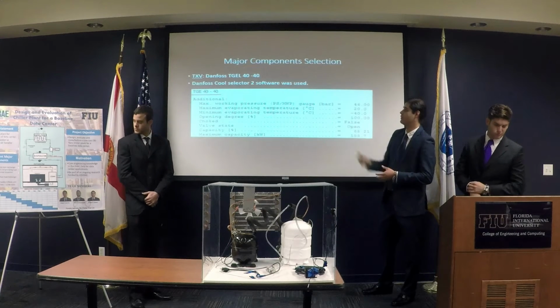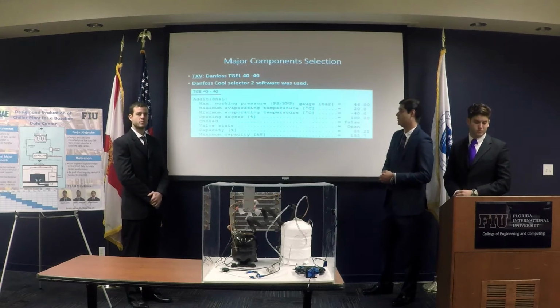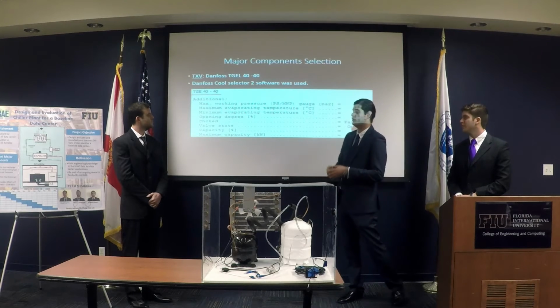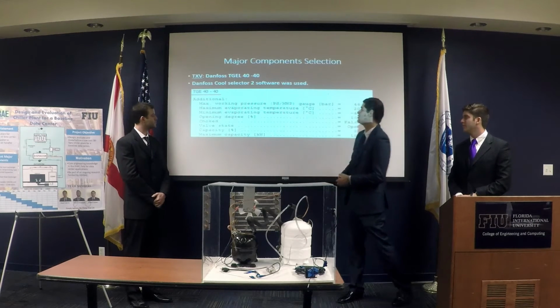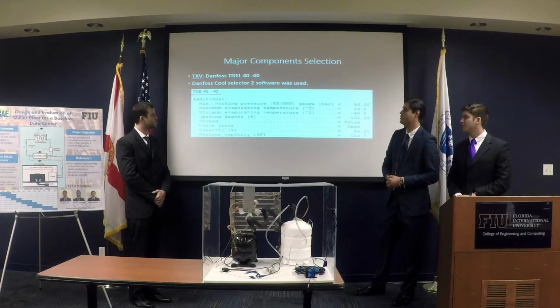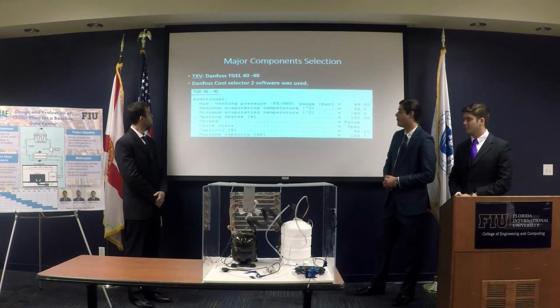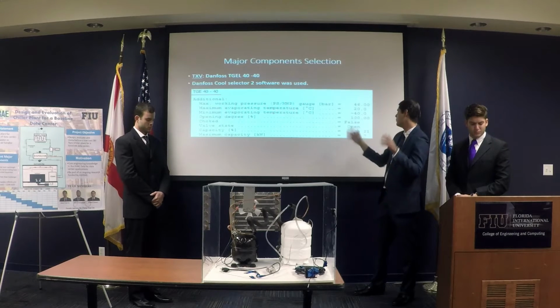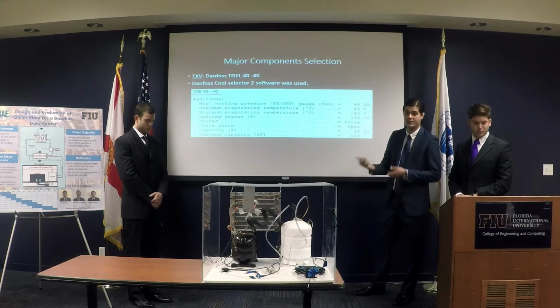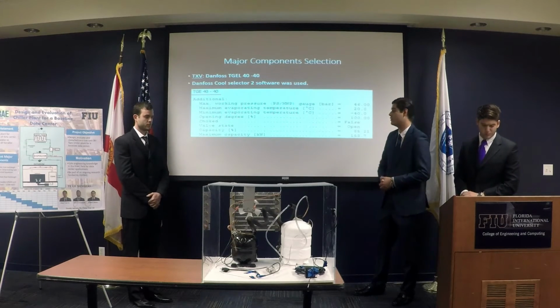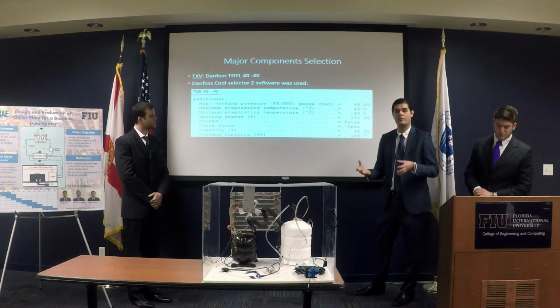And finally, the thermal expansion valve. This is manufactured by Danfoss. And again, taking into account the design conditions, we selected this one, the TG4040. It has a maximum capacity of 153.7 kilowatts, which is more than enough. So this falls within our operating envelope.